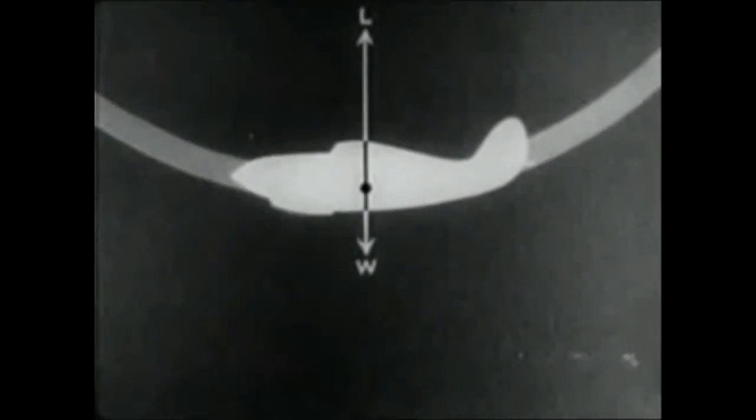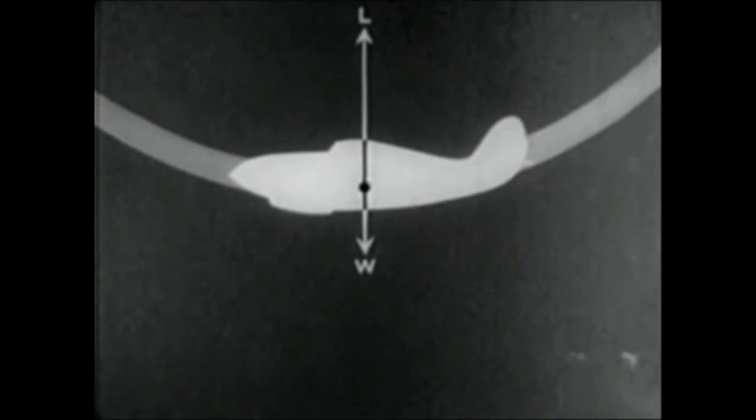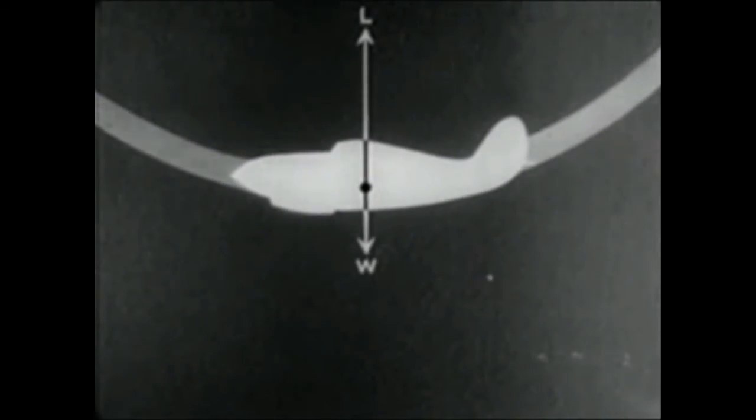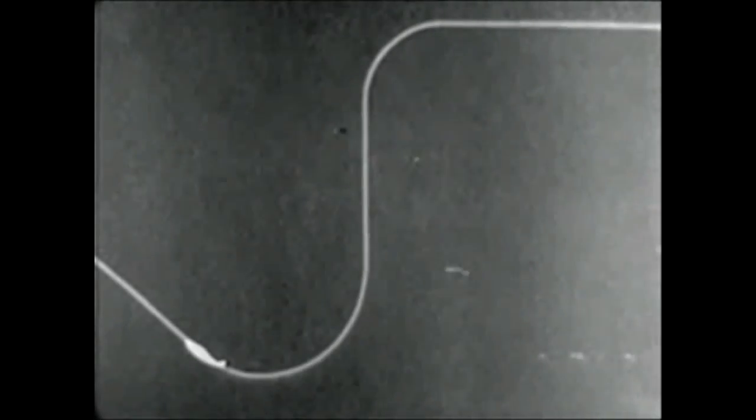In pulling out of the dive, the angle of attack must be increased slowly. During this maneuver, the lift may attain several times the value of its weight. This increase in lift produces acceleration, which in turn produces a curved flight path,